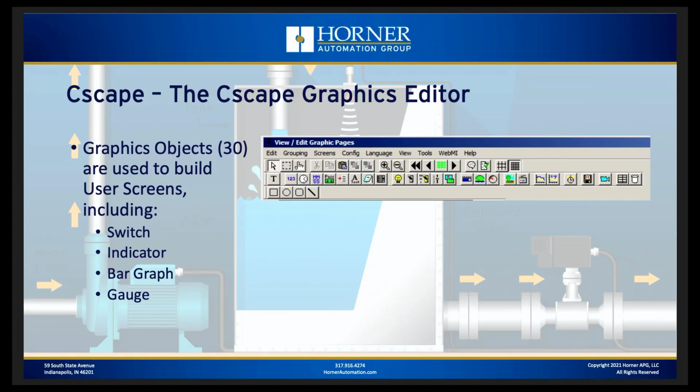As we talk about developing graphics for Cscape, when you're developing screens, whether it's push buttons and pilot lights or trend objects or bar graphs or gauges, whatever the case may be, when you're developing screens for an OCS, you need to open the Cscape Graphics Editor. And then within the Cscape Graphics Editor, you have a number of objects all shown on the screen that you can use to build the contents of the various screens that you present to your user.